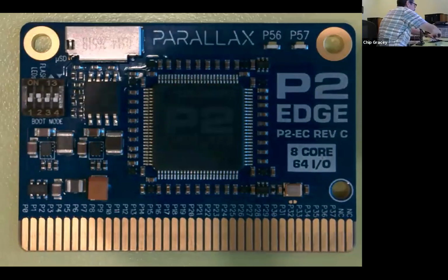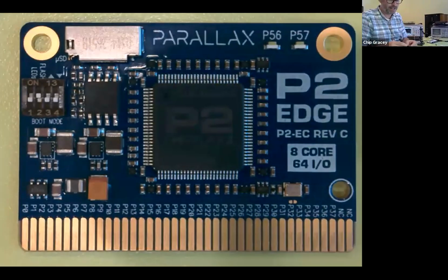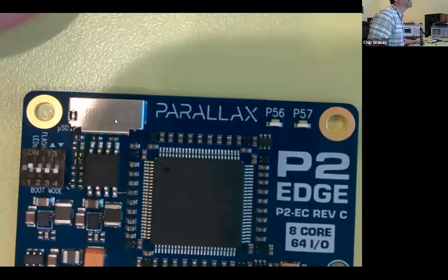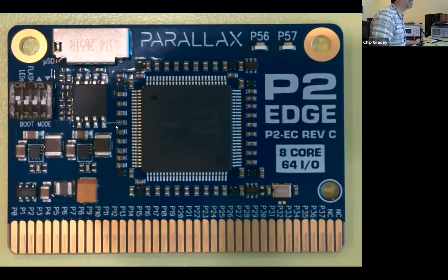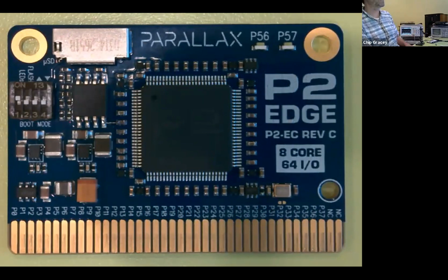I was thinking with Michael, like, man, I don't have a good soldering iron, but I have some ideas I can put on that. So yesterday I made this modification. I found some multi-stranded wire, and I took out one strand, and all I had was some rosin core flux, but I wetted the tip of the iron. I touched that there, touched that here, and then just wiggled it back and forth until it came off. So this is ground, and now this is ground, and that let us test out the flash.